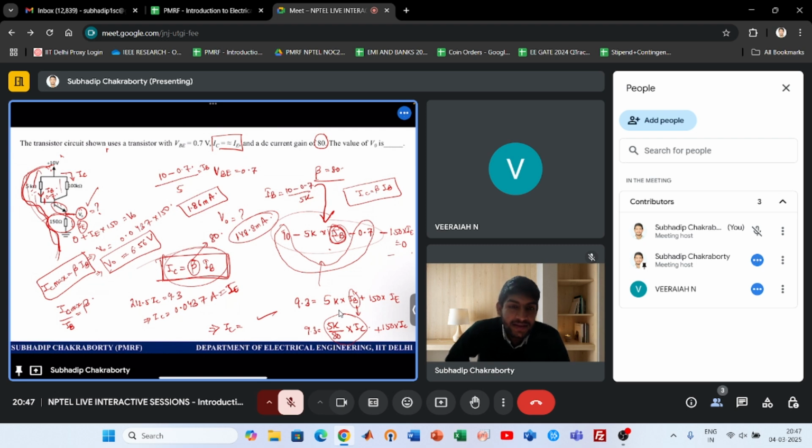By this method. Why this method? Because this method completely calculates the network currents based on the biasing resistor. Biasing resistors are very important. They can completely change the currents. And once you take this biasing resistor into consideration, you see that the IC value reduces.